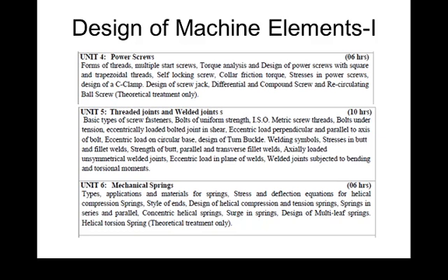A lead screw is also there in the lathe machine, and in your vices the screws are also available. Different applications are there. How to design it, what is its importance, what is the self-locking condition, what different types of threads are there, what a screw jack is. The screw jack is the most popular application of power screw, used in your automobile to lift the vehicle. How to design it, that we will discuss in the design of a power screw.